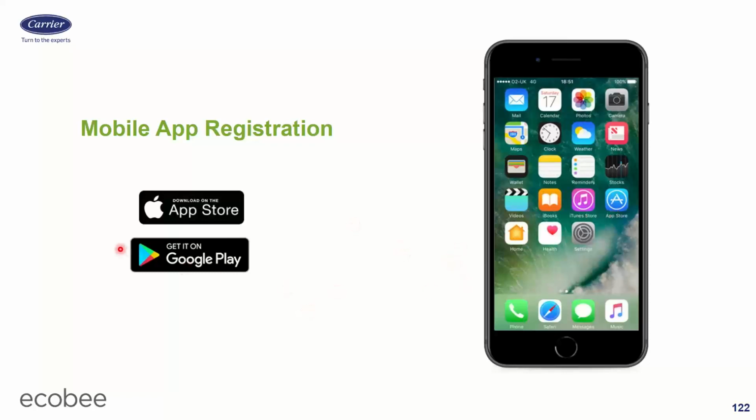Brian asked the question, what features will not be usable without Wi-Fi? So without Wi-Fi, the features that won't work as well are the ones that relate to outdoor air temperature and data trending. A heat pump would be a problem without Wi-Fi, because with the auxiliary heat, I need to know the outdoor temperature to know when to switch between the auxiliary heat and regular heat. So I have to have Wi-Fi because I need the outdoor temperature for a heat pump.